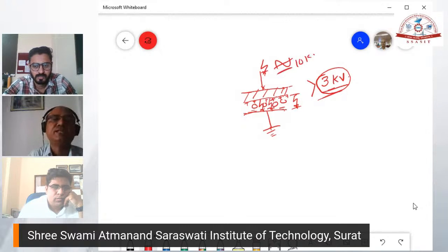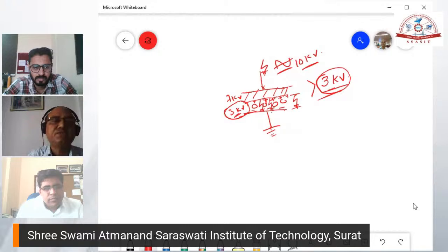The applied voltage will be much more than that because it has to be divided somewhere over here and somewhere over here. Now, the space charge will not affect this 3 kV. If the space charge is sufficient to affect this 3 kV, then you will have a variation. Whatever minor variation of the induced voltage, or reduction or enhancement of the voltage by the space charges, that is going to affect it.